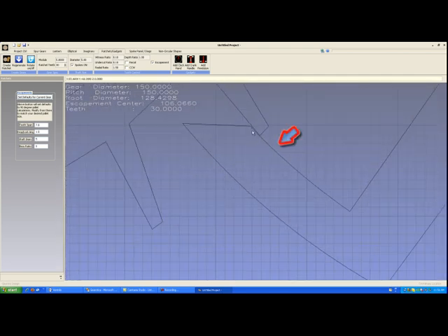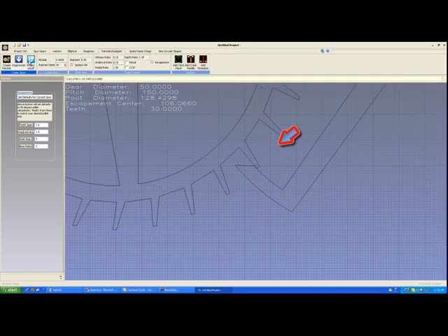It hits the lock face. This is the lock face on the bottom. The process then repeats itself with the pawl going in for its swing. Incidentally, I have the pawl coming in all the way to the wheel on its swing. This typically won't occur in a pendulum. If it does, you have too much weight and you're pushing it.